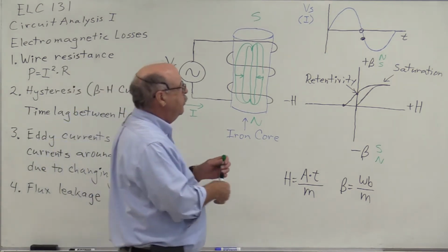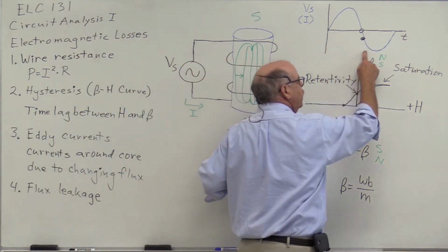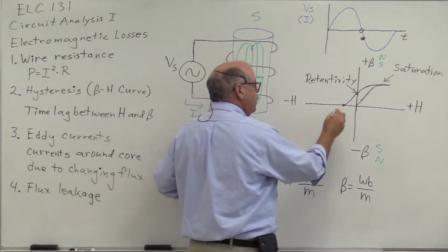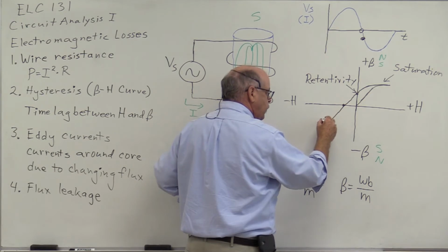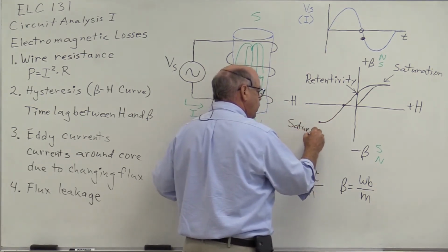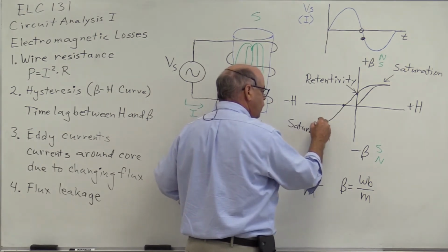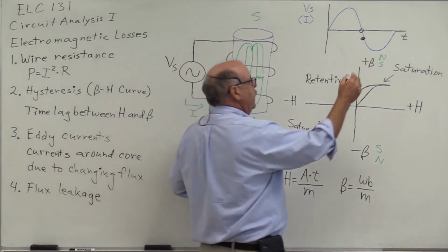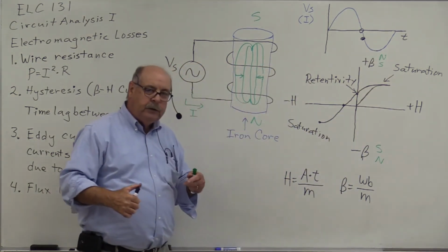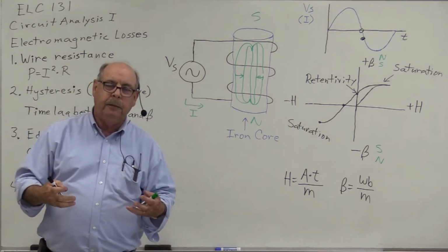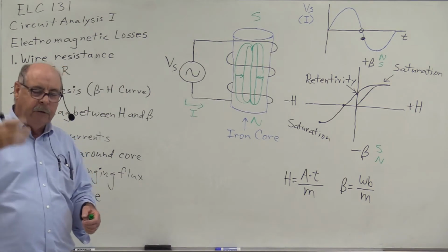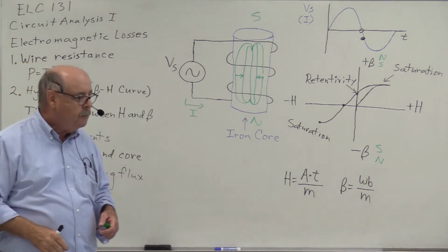As I keep increasing current in the negative direction, if you will, of course, magnetic flux will increase and again reach the point of saturation, meaning that it doesn't matter if I keep increasing current in the negative direction, the flux can only get so big because there's only so many atoms for d orbital electrons to be pulled up in.